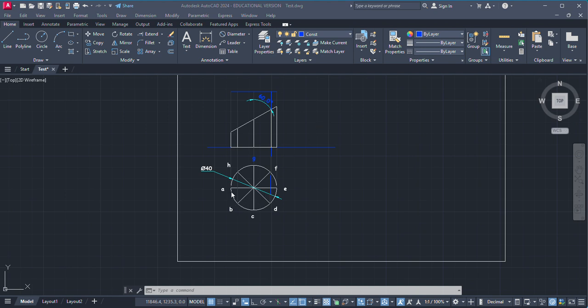So after opening this arc, we will get a small rectangle. The length of this small rectangle will be 125.6 divided by 8, that is, 1/8 of the circumference, because these arcs are of equal length and they are in 8 equal parts. The total circumference is 125.6, and to get this arc length, we divide the circumference by 8. So this arc length is 15.7, and the height we already have is 50 mm.